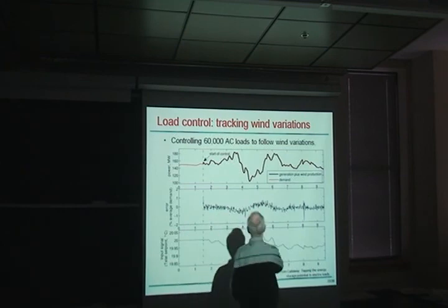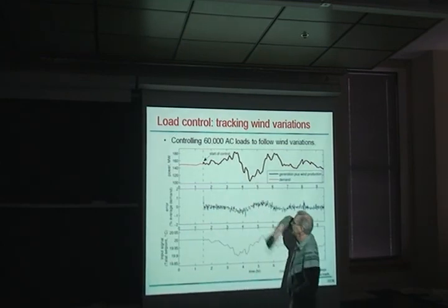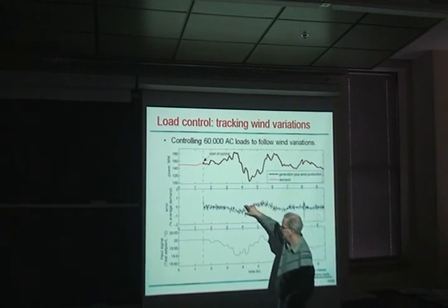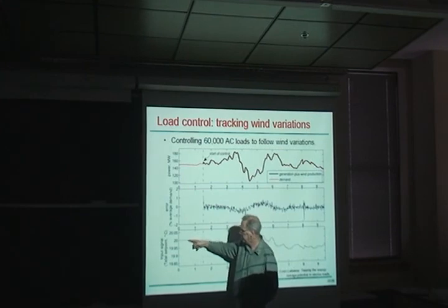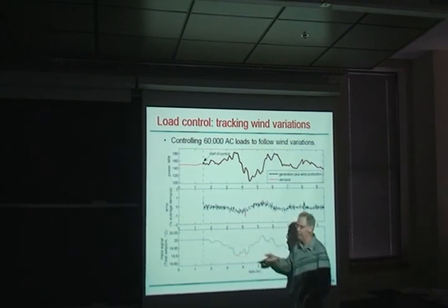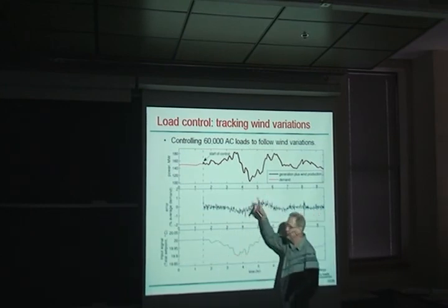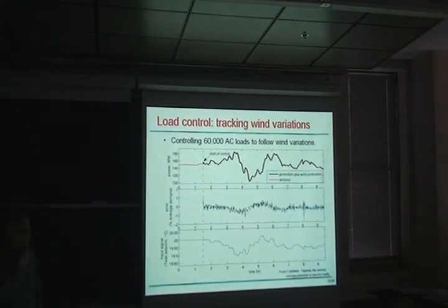So, we're talking hours along the scale here. There's variation that's happening. This is the error. This is the level of controllability that's required. So the nominal set point is 20 degrees Celsius. The maximum deviation is 0.1 of a degree Celsius to create a significant change in total load from the air conditioner. So it works very well.